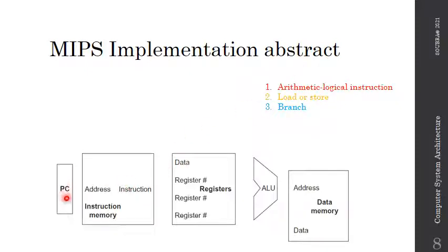All right, so I'm assuming that you paused the video and now you're trying to verify your answer. Let's start with number 1. For ALU instructions, do I need the PC, the program counter? Naturally, for any type of instruction, I need the pointer to tell me what is the instruction that I'm going to execute. So definitely the PC is needed for the ALU instructions, because it will be pointing to the actual instruction that happens to be an ALU instruction. So this is definitely needed. What about the instruction memory?